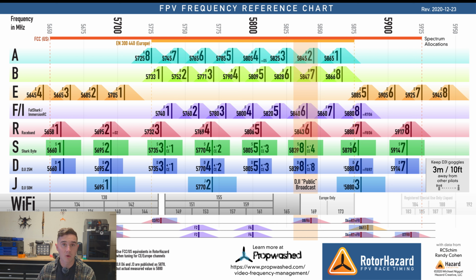For programming your drone on what video transmit system you're going to use, it's going to depend on whether or not you're analog or HD. Fat Shark has their own bands and their own channels, just like DJI does. The other bands are analog. Most people fly on race band, which is what I recommend, just because there's already that gap. So there's different bands for you to fly on. I put on the screen a quick sheet of all these, but let me explain them to you real fast.